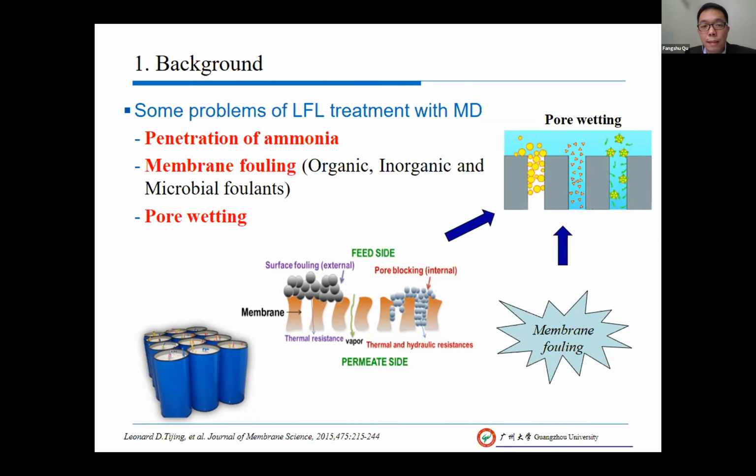We discussed a lot today. The pore wetting can completely destroy the separation performance of the MD, so it's a very fatal problem. But the application of the MD in landfill leachate treatment is not extensively investigated. So that's still something unknown, for example, the key foulings and the fouling mechanisms. So we need to do more investigations about this topic.